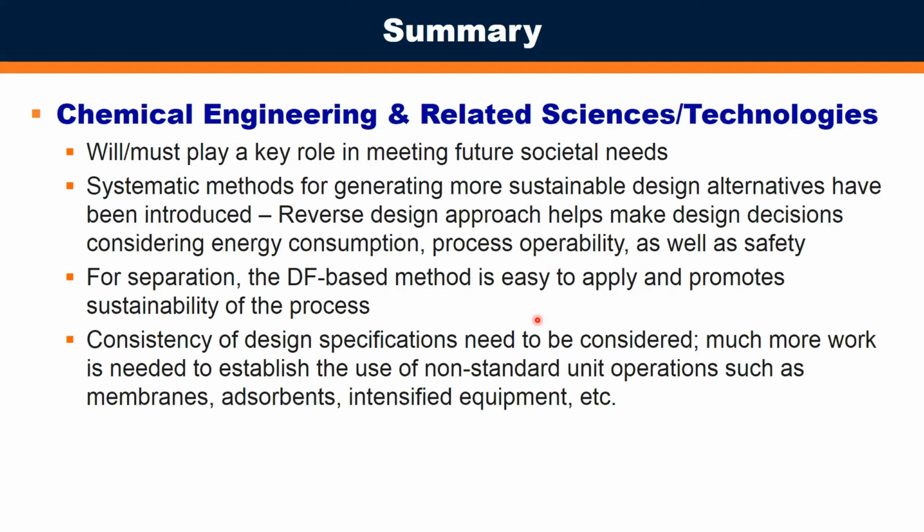We do need to be very careful about consistency of the design specifications. We need a lot more work in our field to establish the use of the more non-standard unit operations, things like membranes, adsorbents, different types of intensified equipment, and so on, that are not readily available in commercial process simulators. We need to make sure that these are done in a consistent way so that we can get good results when we use them in the simulators for design purposes.